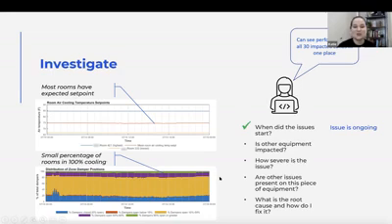So this one actually shows you the distribution of your VAV box dampers. So your air handler serves air to each of these zones, and this damper will modulate to bring in more or less air depending on whether you're in heating or cooling or what the demands of that space are. If you're in cooling, you would expect those dampers to be open because you want as much cold air as you can into that space. So I would expect to see lots of dampers wide open if I thought that there were lots of zones that were demanding colder temperatures.